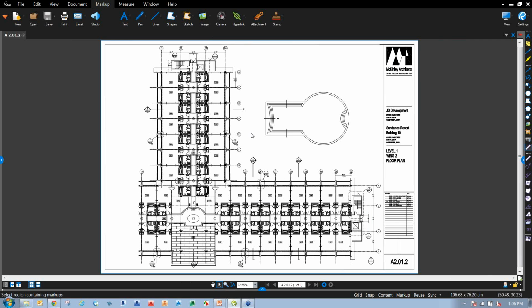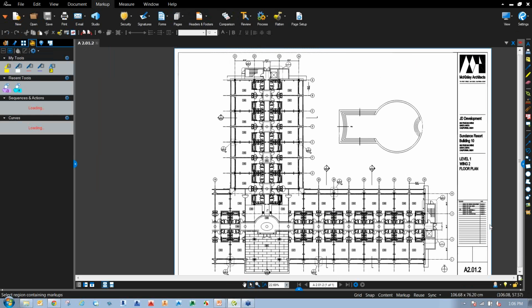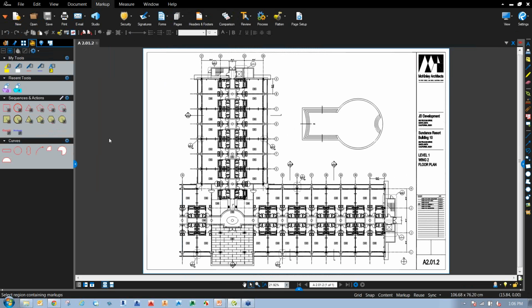The screen that you see here would depend on what we call our profiles. The concept of profile is very similar to the concept of workspaces in AutoCAD, if you have ever used AutoCAD. So down the bottom, I've got my profiles button. Currently, I'm in the design review profile. If I, for example, go to the construction profile, it adds some toolbars here, opens this left panel bar, shows me some of these tools.